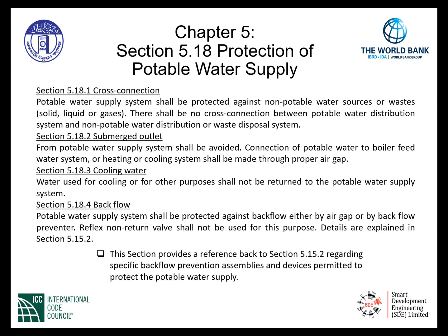Section 5.18.2, Submerged Outlet. From potable water supply system shall be avoided. Connection of potable water to boiler feed water system or heating or cooling system shall be made through proper air gap.